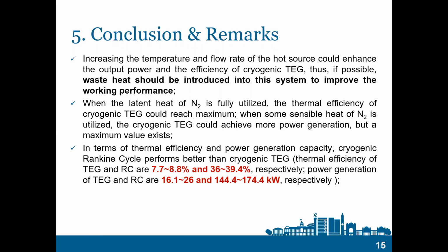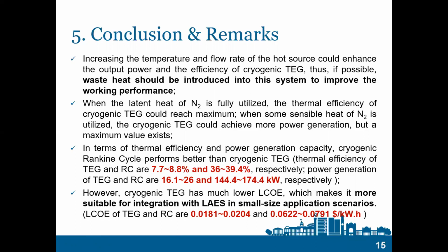Third, in terms of thermal efficiency and power generation capacity, the cryogenic Rankine cycle performs better than the cryogenic TEG. However, the cryogenic TEG has a much lower levelized cost of energy than the cryogenic Rankine cycle, which makes the cryogenic TEG heat exchanger more suitable for integration with a liquid air energy storage system in some small-scale application scenarios.